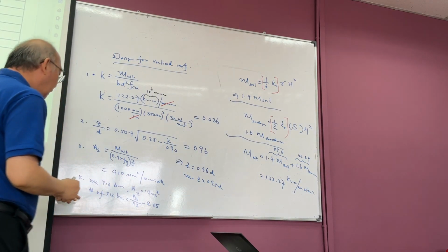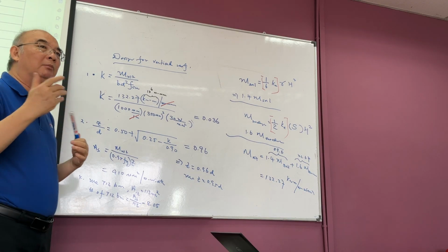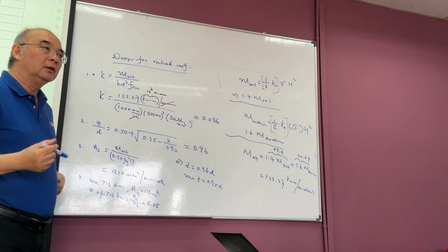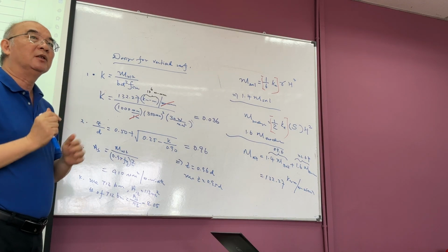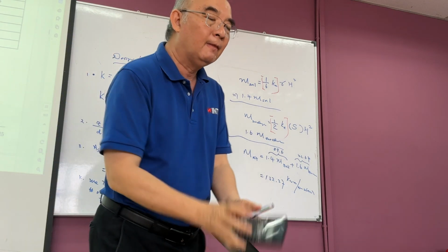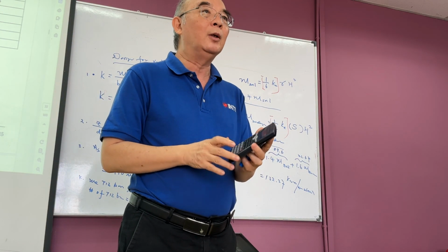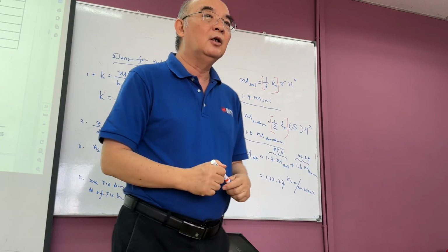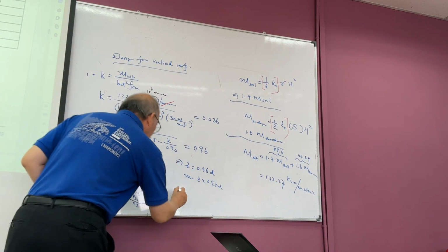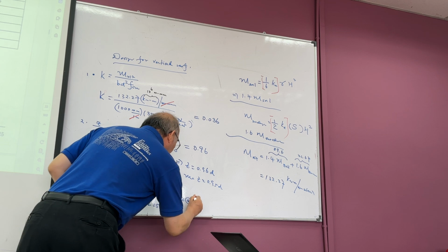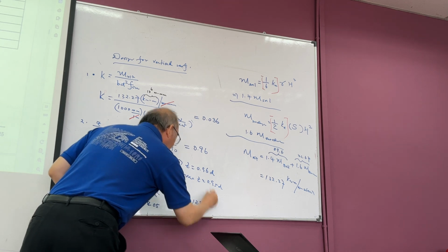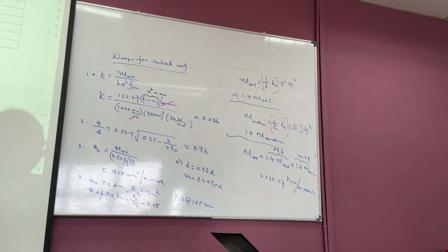So if we use 8, then we have to see, okay, 8 number of bars per meter. So what's the spacing? It will be 1000 divided by 8, right? So 125. Correct? So that means we are using T12 at 125 millimeter. Understand?